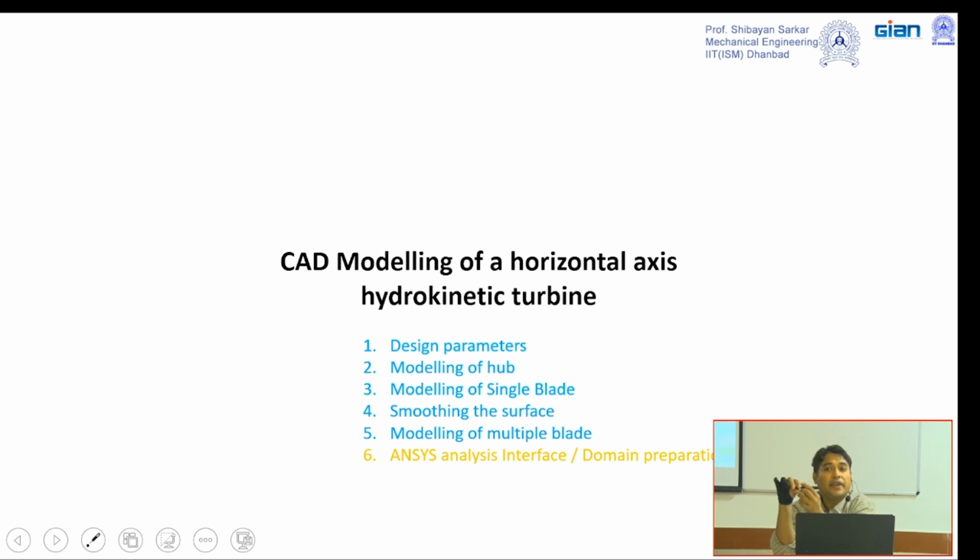Then I have to make an arrangement: either you change the direction of the shaft rotation through a bevel gear maybe, but if I am putting in a bevel gear, there will be mechanical loss. Otherwise, you have to prepare some sealed environment to keep your generator here, and again it will be creating a problem.